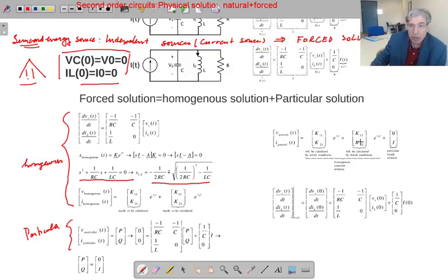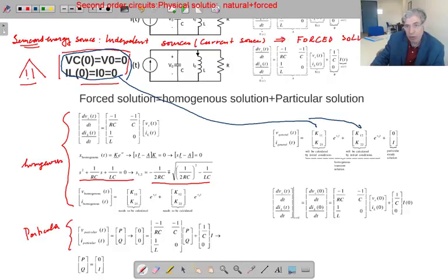Now we are going to calculate these k values. How we are going to calculate it? We are going to use the initial conditions. So let me make it a different color. So these are the initial conditions. I will be using these initial conditions for the calculation of those two. Once again, there are two initial conditions here, inductor current and capacitor voltage. But we've got 4 Ks here to be calculated. So we need to calculate the initial conditions of the derivative variables.